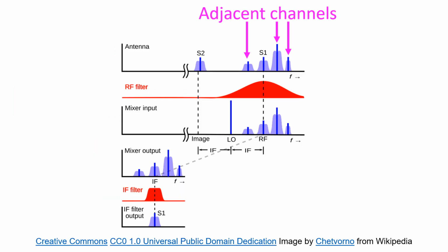Adjacent channel interference, as the name implies, is interference caused by signals near to the intended frequency in the receiver. It could be due to improper tuning of the radio and sometimes due to poor frequency control in the transmissions, like drift in the variable frequency oscillator (VFO) frequency.